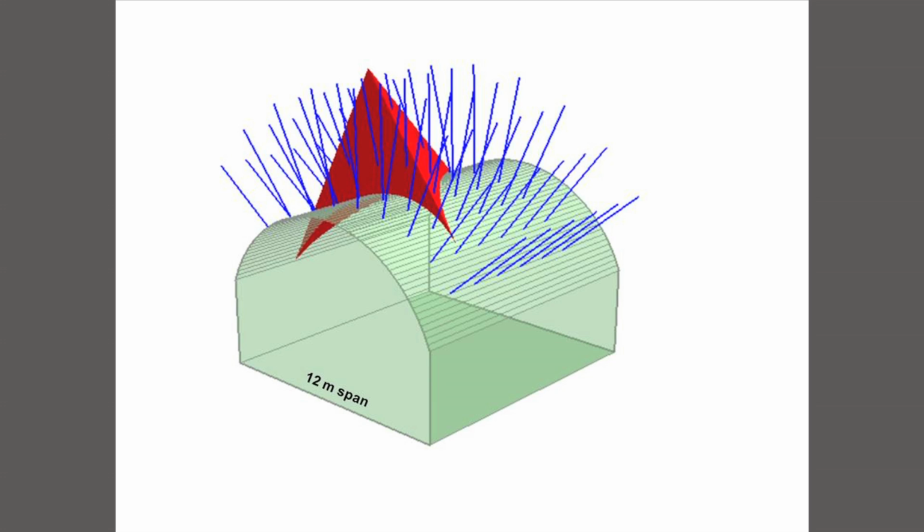Unfortunately, it's not quite that simple, because the question then arises, and this particular tunnel was 12 meter in span, taken as a top heading and then benched down another 10 meters. So it was the tail race tunnel of a hydro scheme, and 12 meters span, 18 meters high. So we're looking at the top heading, the first 8 meters of excavation. And to go in there and install rock bolts is not as simple as it sounds when you say it.